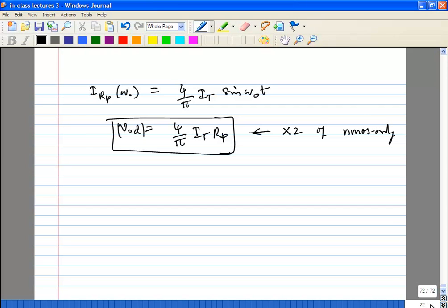So it's actually pretty straightforward. You want to design for a particular amplitude and a particular power consumption. So let's say you start with the power consumption, you choose a particular current. Then once you know the particular current, you design the inductor for a particular RP. As far as phase noise is concerned, you want to maximize your swing, so you would try to maximize your inductance, which would maximize your RP.